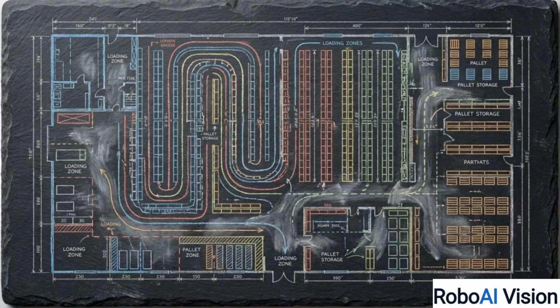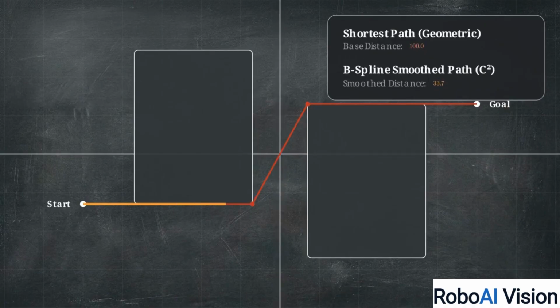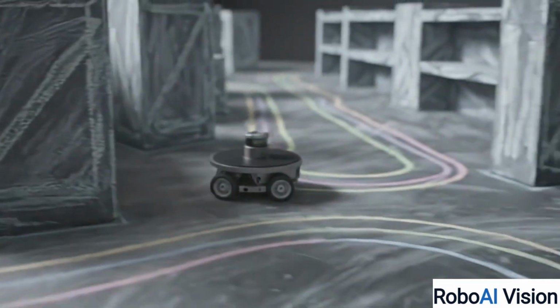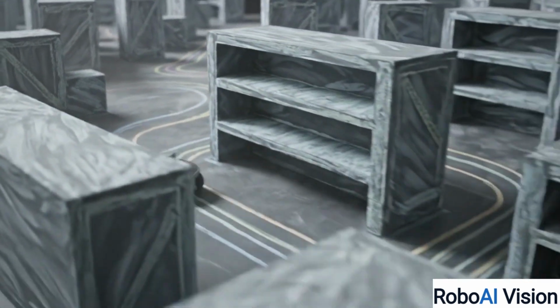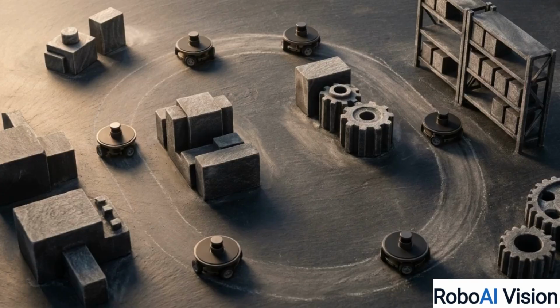There is exactly one metric where the B-spline approach mathematically underperforms: total spatial path length. Because the spline rounds over the interior corners, the final route is marginally longer than the absolute shortest geometric path found by the initial search. But this spatial sacrifice yields massive physical dividends. Adding a few centimeters eliminates start-stop cycles, preserving momentum, slashing mechanical wear, and conserving battery energy. By integrating cubic B-splines into the navigation pipeline, the acceleration paradox is solved. It elevates a theoretically perfect map route into a highly efficient, production-ready framework for real-world autonomy.